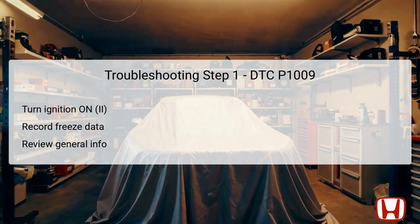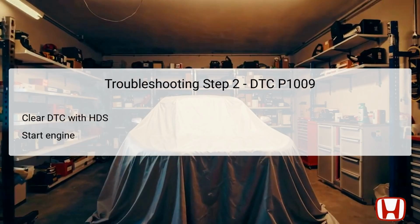Additionally, reviewing the general troubleshooting information is important before diving deeper into specific components. This overview allows the technician to focus on common issues associated with the code before starting with more complex diagnostics. In this second step, utilize the HDS, Honda Diagnostic System, to clear the DTC from the system. The HDS is a specialized diagnostic tool designed for Honda vehicles and provides both monitoring and troubleshooting capabilities.